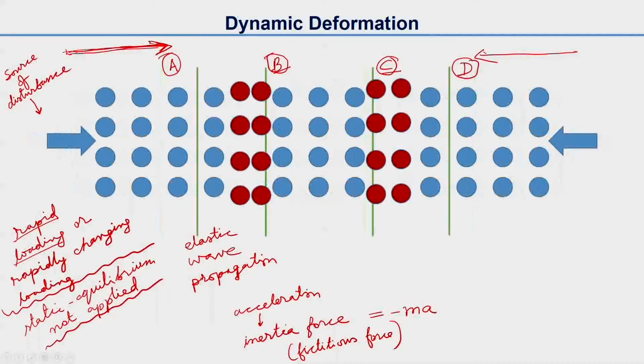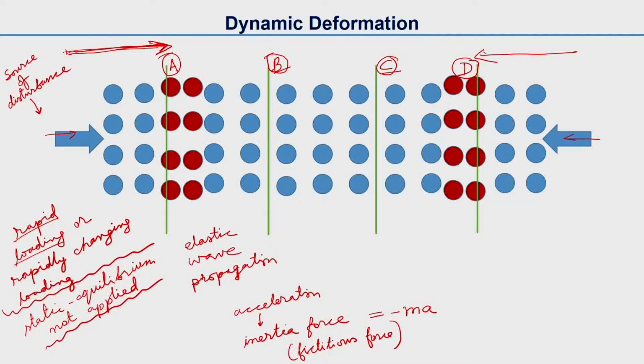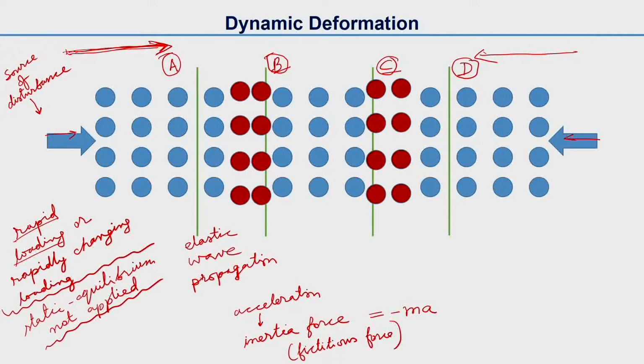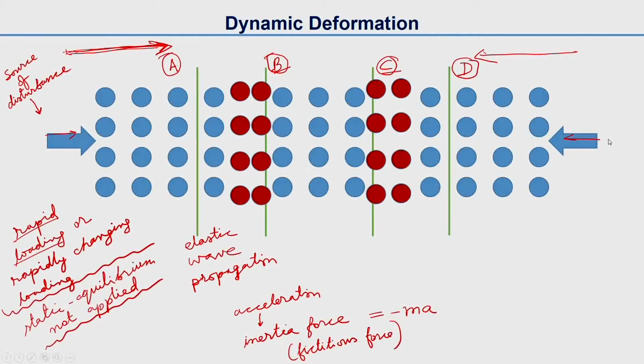So I am running this animation again. We were deforming from both the left side and the right-hand side. What is happening here is this group of atoms is moving towards each other. Now how can you determine how many vertical rows of atoms, in this case we have only 2 rows, will be grouped together, and these atoms will move towards the other side of the body.